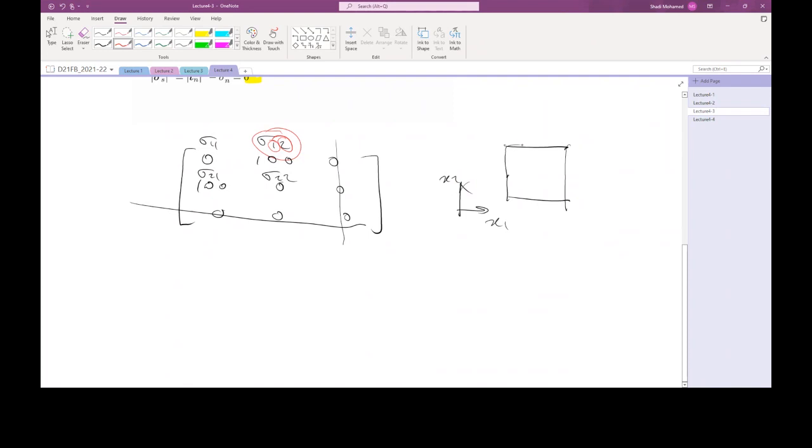Okay, so you only have a shear component here, and this amount is 100. Now you look into the second one, this is T, or sigma 2,1. It is active on the plane that is identified by x1, which is this plane here, and it is in the direction of x2. So it should be positive, positive, positive, positive. It's in this one.